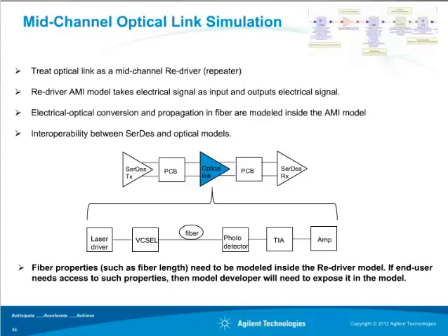If you look at it here, we think of the optical link as a redriver. That's kind of like a general term. So this could be electrical as well as optical at this particular position. The redriver model takes electrical in and gives out electrical. That keeps us in the electrical domain inside the channel simulation. All of the E to O and O to E stuff is done inside of that model. And this allows us to put this together with different SerDes models.